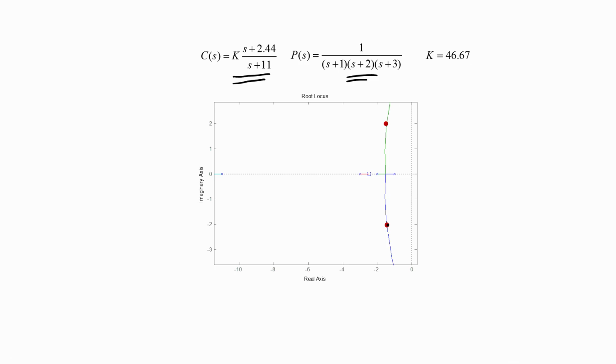So, we would have one more pole on this branch of the root locus between this pole and that 0, and another pole on the other branch of the root locus, that is somewhere here. So since these poles are not as close to the origin as the two poles minus 1.5 plus minus 2j, they will not dominate the response of the closed loop system.